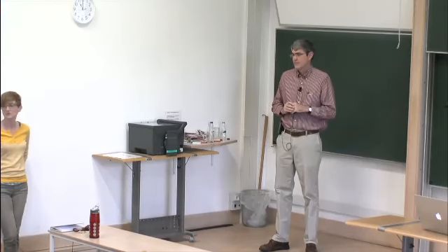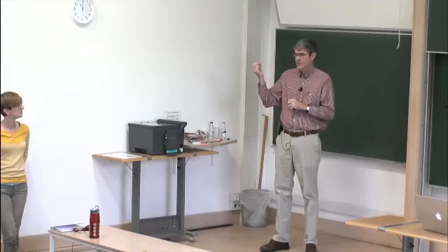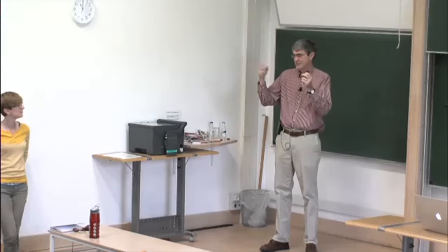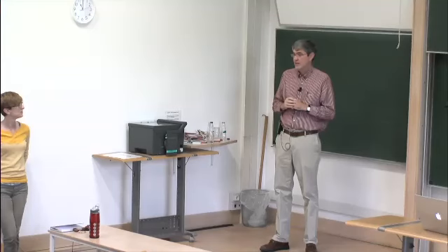I mean, I guess you know why that's a controversial thing to do in at least some circumstances, right? So there are situations, for example, where you have variable coefficient advection, where you might want the advection velocities at the edges. So when we look at variable coefficient velocity, if you're given the velocity field anyway, then we do actually look at evaluating the velocities at the cell edges, or some average of the normal velocity across each cell edge, which is what we would really be using in our Riemann solver.